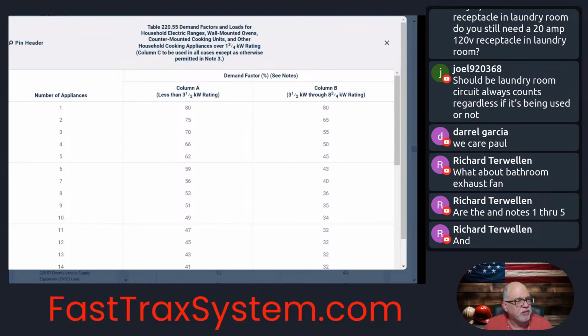That'll help you because you see this percentage right here, but a lot of people get confused when they see these. This is not demand values. These aren't kW values, okay? These are percentages. I know some students will put a little dot beside all of these because converting these to decimals, you start from the right and move two spaces to the left, right? Again, don't do that if you're in a state where you're taking an exam and they don't let you write in the code book. But if you are, you can write in there. You can highlight the percentage here. You can put a big percentage symbol right here. Anything that reminds you of that, okay?